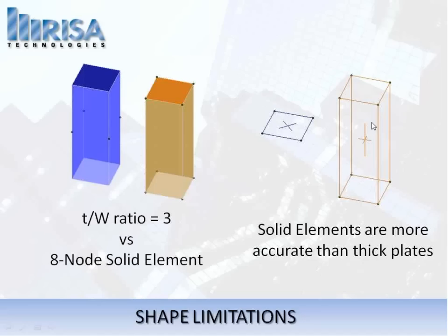Now, you may ask yourself, well, why wouldn't we just use solids for everything? We could model all plates as just really short solids if we wanted to. And yes, it's true you can, but when you go to a solid, you're now looking at much more results to sift through. And in fact, because the quantity of results are so much higher, we actually can't present nearly as many of them to you.